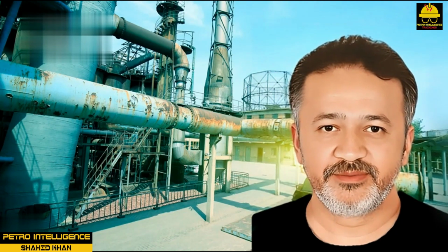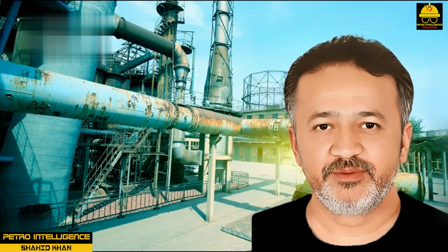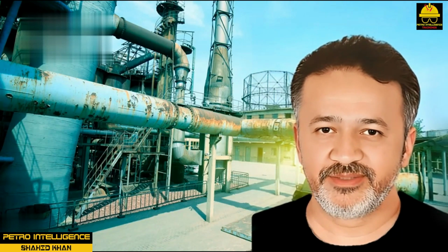Nitrogen hose connections are located at utility stations in the process units. These connections are used for nitrogen only and are different from the connections used for air, water, or steam. The nitrogen connections, a national standard coupling, are welded to prevent them from being changed to other types of fittings, namely air or water.